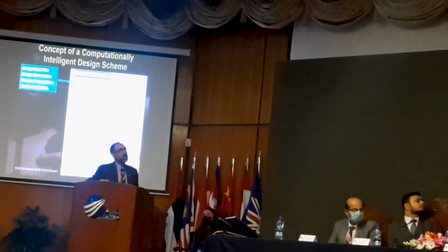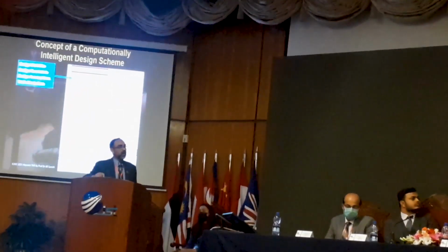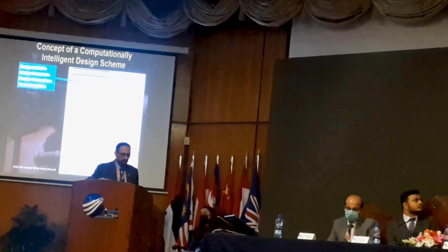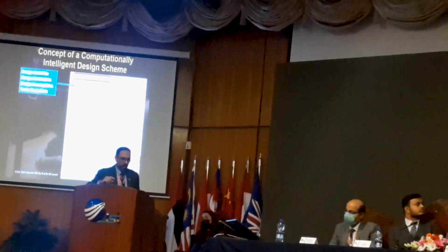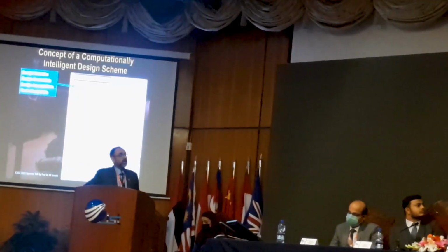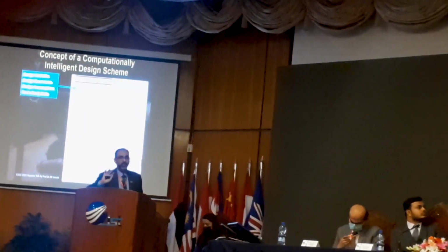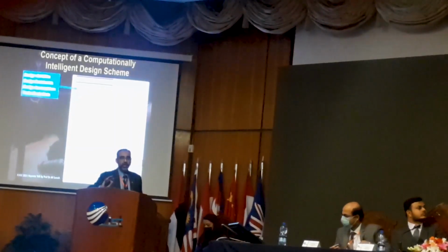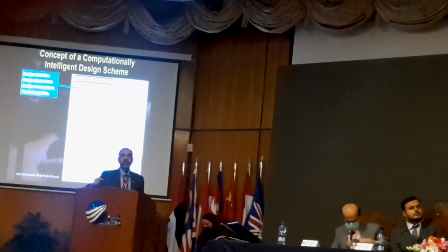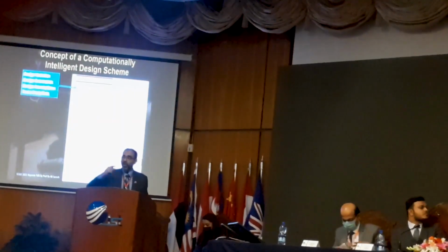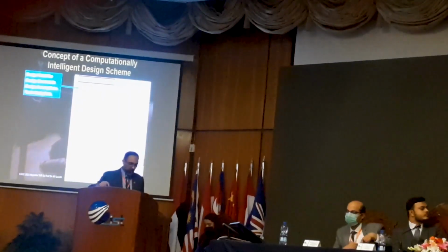This is a long process, and once this long process is done, then the process of the actual classical design scheme starts, where we establish the baseline, then we carry out the aerodynamics, the propulsion, weight, trajectory, performance studies, and then after all the decisions have gone through, we take into account some figure of merit to see whether we have achieved what we were looking for. And if it is achieved, then we will go for the sizing process, and then the iteration cycle begins all over again. And so it's an iterative process, goes again and again and again.